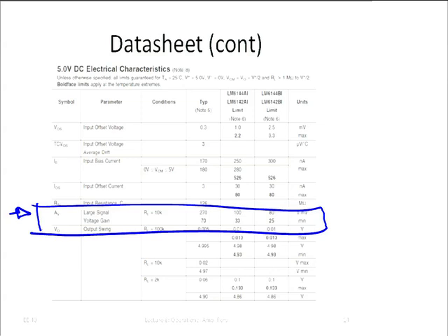Many operational amplifiers, probably most, will have a gain around here, maybe even a little bit higher. But you know, if the temperature is low or whatnot, and your operational amplifier has only this gain, it still should work. The thing that you built still should work, and you probably know electronic circuits that you have purchased that work most of the time, but sometimes they don't work. It's frustrating, right? And so don't be a frustration designer, right? Make sure that you are a good, reliable designer, and so you have to design so that it still works with the lower numbers in the data sheet.